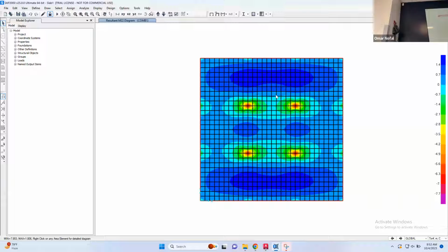Okay. And to do a model for the entire building, you need to initiate some parameters. You need a value, like what is the column size? So how can I get that? What we do is, if this building is 10 stories, I take one story and do a 2D analysis, get the beam sizes, get the slab sizes. Based on the bending moment, I decide on the reinforcement and the slab thickness.